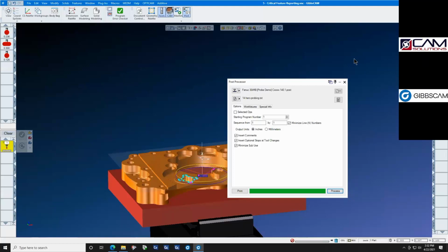And your standard probe has 40 millionths accuracy. That's the OMP 40 or the OMP 60. Now, if you had elected to buy an OMP 400 or an OMP 600 Renishaw probe, the accuracy of that probe is 10 millionths of an inch. So the probe itself, its accuracy is not in question.